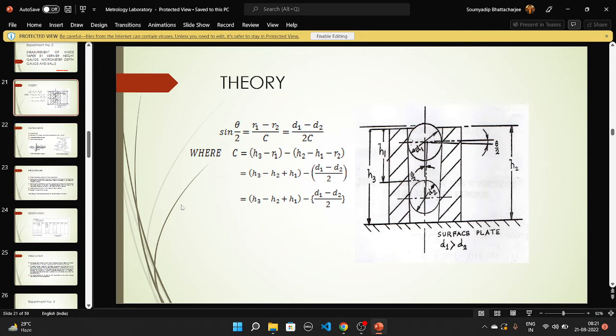And this is the one difference with the regular micrometer. Another difference is that the depth micrometer is graduated in the backward direction. It is the reverse direction, right? It is not starting like 0, 5, 10. You start from, say, 25, then 20, 15. So it's in descending order.